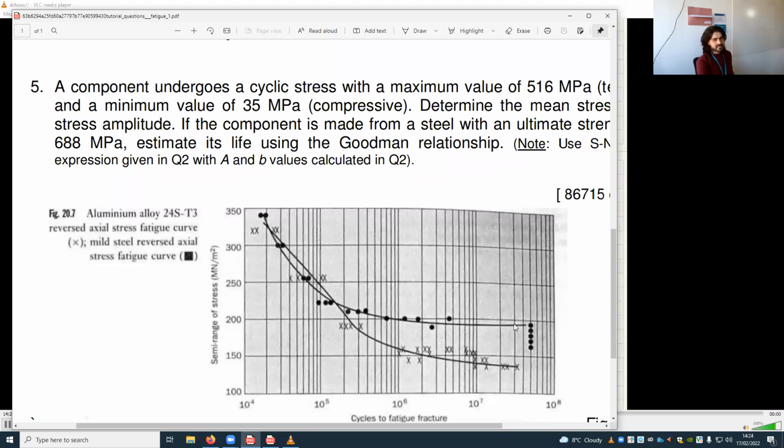And this curve has, as you can see, a specific endurance limit. What is the endurance stress of this curve? So what is the stress below which I'm always 100% safe? Say again? 190. Yeah, that looks like it. See, this is 200, and this is a bit lower than 180, 190.